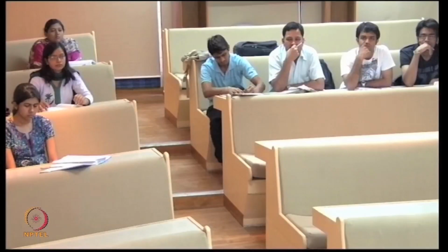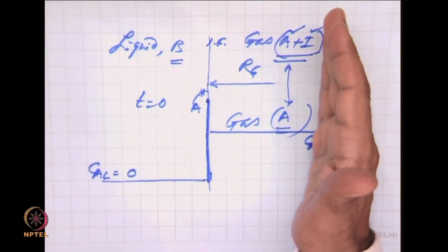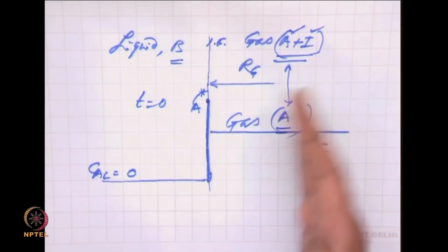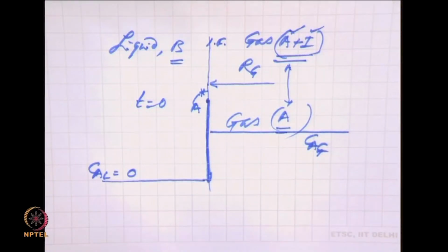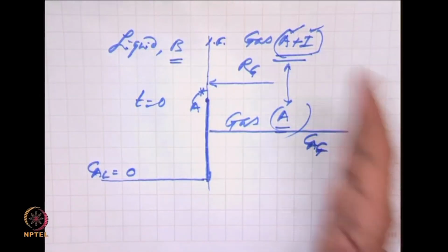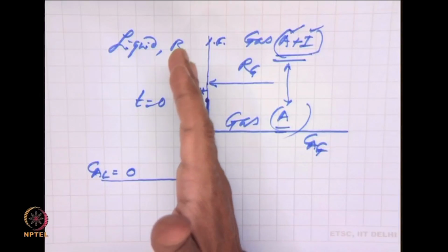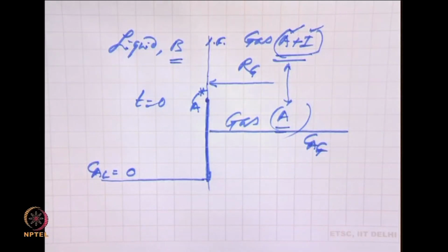The thermal kinetic energy will permit molecules of A to move at certain velocities. They can only come up to this surface at some representative velocity corresponding to that temperature. And since the temperature is finite, that velocity is finite, and the strike rate is finite. Therefore, the gas does not have more than a certain amount to be supplied per area per time, although the liquid has the capacity to transfer much more than what is actually made available.